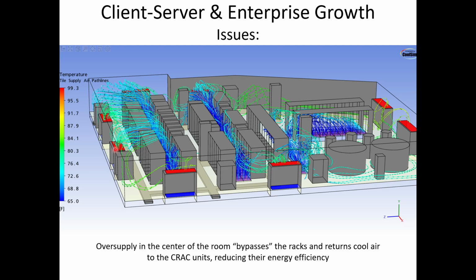The way to make a good heat exchanger better is to provide a substantial delta T, change in temperature, between return and supply. Bypass airflow tends to cool off the return and therefore make the efficiency and the cooling capacity of this device decline.